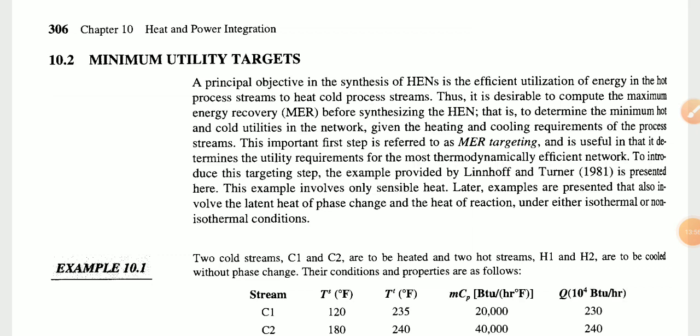To introduce the targeting steps, the example provided by Linnhoff and Turner is presented here. This example involves only sensible heat. Later examples are presented that also involve latent heat and phase change, and the heat of reactions under either isothermal or non-isothermal conditions.